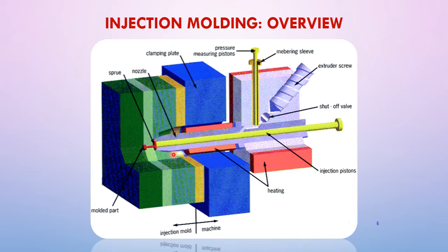The entire process is to be carried out under variothermal condition. The variothermal condition was already described in the previous slide. The melt temperature should be near to the maximum process temperature of the polymer to be replicated. When the microcavity is filled properly, the mold halves are to be separated at appropriate temperature without any lateral offset. You can see the whole process in the video link that is provided.